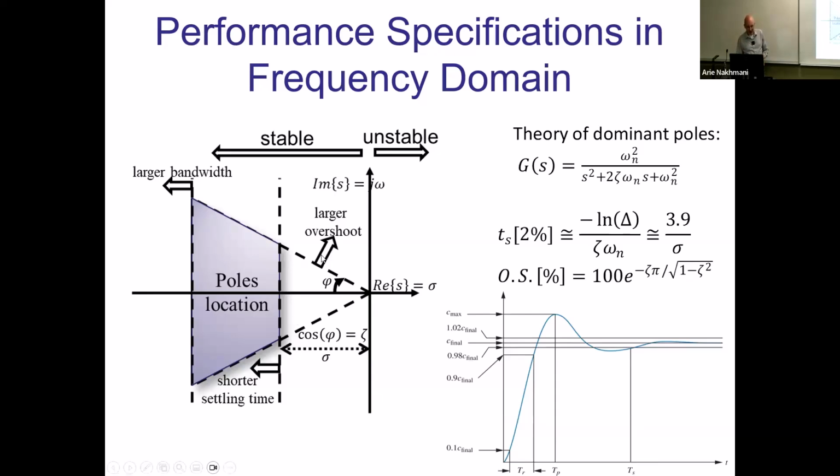Now, that angle of that thing is overshoot. And you have formulas connecting the dominant poles from that function to particular angle phi. And larger the angle is, higher the overshoot is, or stronger the resonance is. So all the things are connected. So it's more oscillatory behavior if it becomes more complex, okay, farther into the complex domain, which means bigger angle of phi.